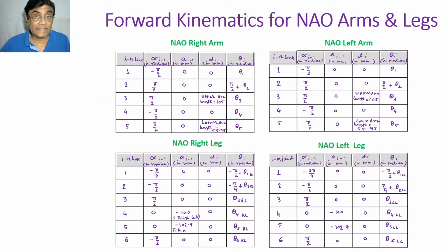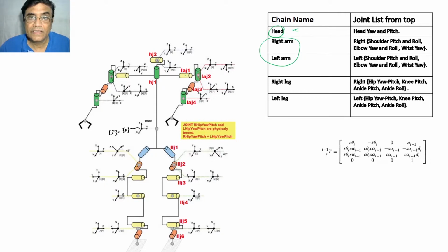So what we will have to do, basically, from the coordinate frame as had been attached here, you see, left arm joint 1. This is joint 2, joint 3, joint 4, and this is joint 5. This is the wrist joint, and so these are the 5 degrees of freedom it has, and accordingly the coordinate frame has been attached. The Z axis is always aligned in the direction of motion. Wherever you find a motion axis, you assign a Z axis. Those things are repetitive in nature, but they are important to know.